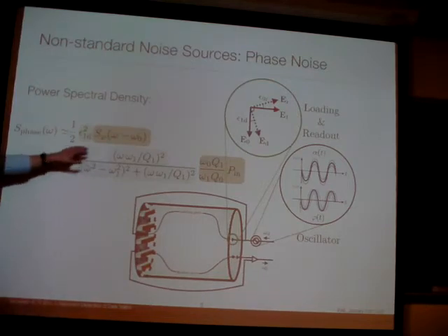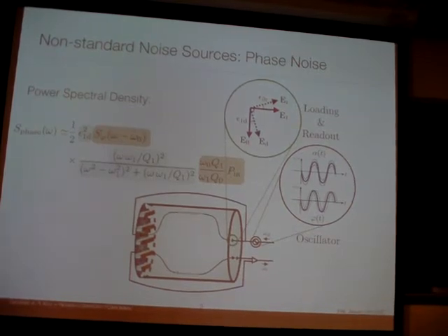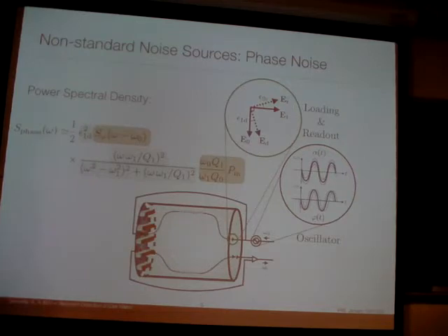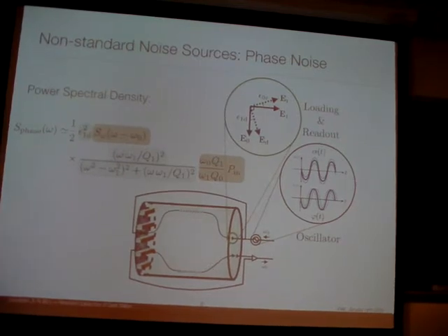And so this power spectral density of the phase has bits that are flat, so frequency independent. It has 1 over frequency components, and it also has 1 over frequency squared and 1 over frequency cubed components. So as you can imagine, as you go to lower and lower separations between the two frequencies, when you're nearer and nearer the peak, this is going to become rather important.